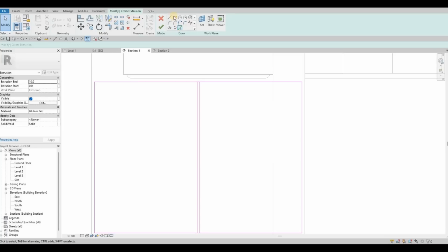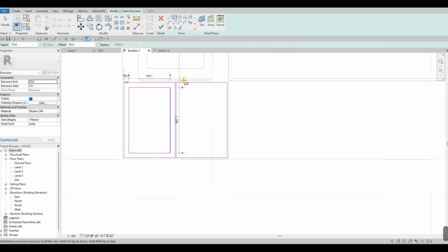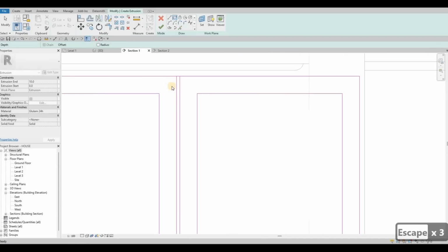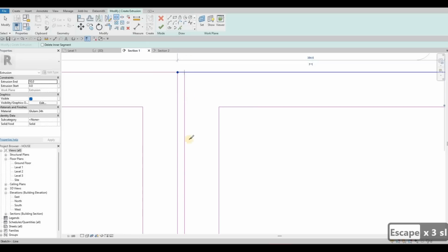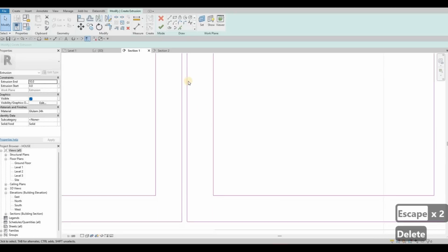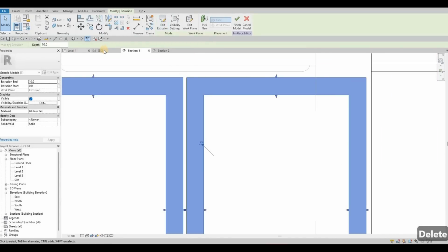So what we can do is we could click rectangle and then do an offset. I'm just going to offset this one to probably 50, and then from this, and then space bar, and then to the edge as well. And then here to the edge as well. And then now SL here. So split element on both, and then split element on here, and then we could just delete this one right here. Click finish, and then we could see how this one looks.